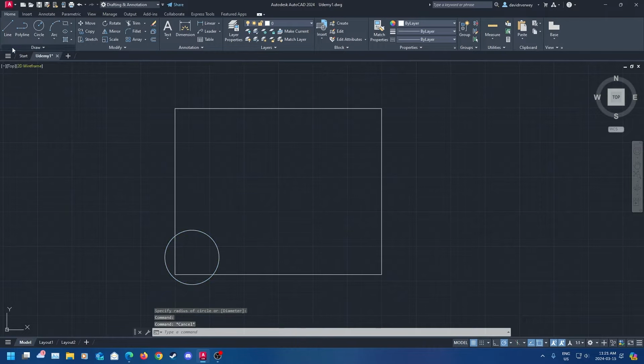So what you're going to do is click circle, like I just did. I completely forgot to explain it. Click circle, and you're going to draw out a circle that is about 3 feet. Mine's completely off. It doesn't matter how big it is for you. Just make sure it's around 3 feet. Once you have that, you're going to want to move. So select the base point.